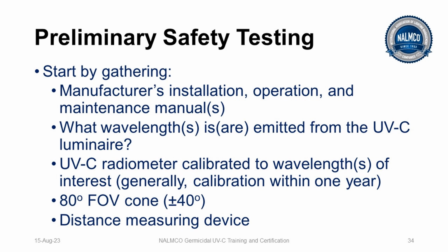Let's talk about preliminary safety testing. We start again by gathering the manufacturer's information, their installation, operation, maintenance manuals. Make sure we understand what wavelength or wavelengths are emitted from the UVC luminaire. You need to have a radiometer calibrated to the wavelength or wavelengths of interest.